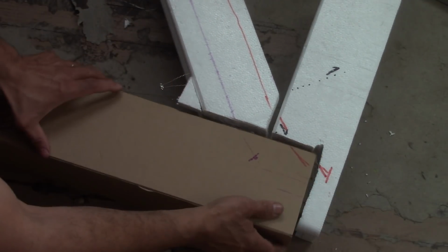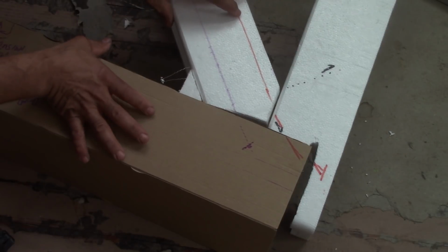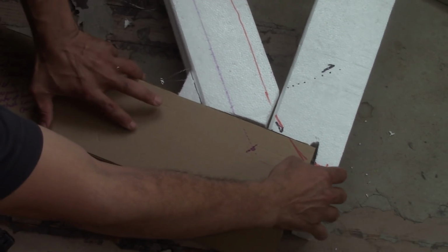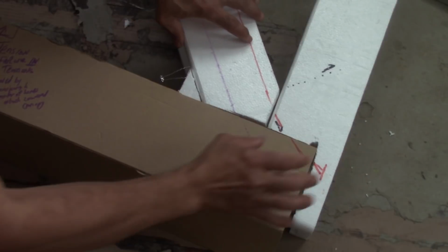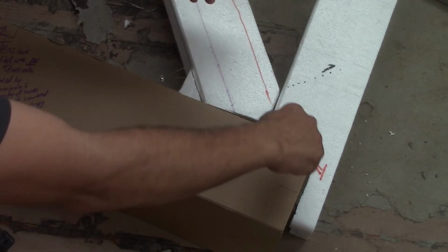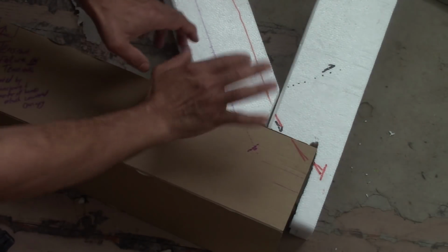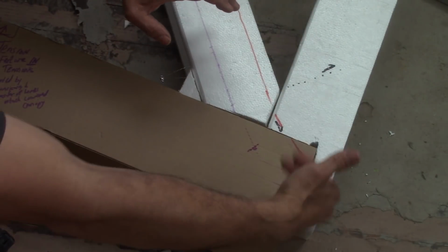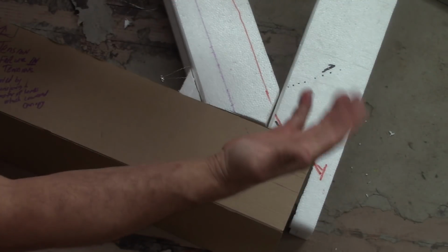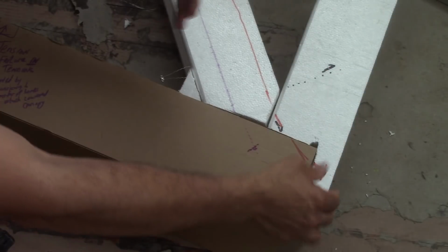Now later on, we got 4 or 5 days of creep going on. Let's advance it. So we no longer have the clamp force on this one. That rotation I showed you, we got a separation right here on the deck, so it rotated a little bit on top of the deck as it caused a tension shear break in the back of the girder system at that point, when you're looking from the rear. The loads are on the back.